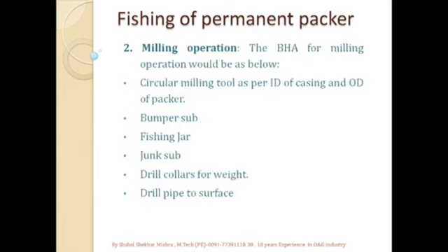So in milling operation, the BHA should be as below: circular milling tool or washover as per ID of the casing and OD of the packer.